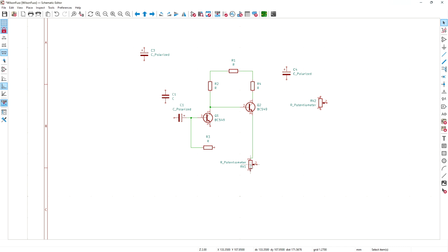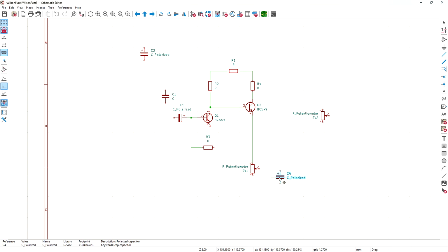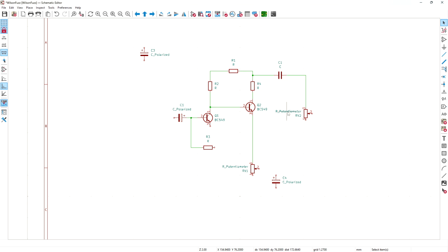I'm just going to wire it there, and if I move it, you can see KiCad keeps this connected. Okay. I'll just press Y, rotate this. This is going here. R is going here. And click, and you can move this wherever you want.